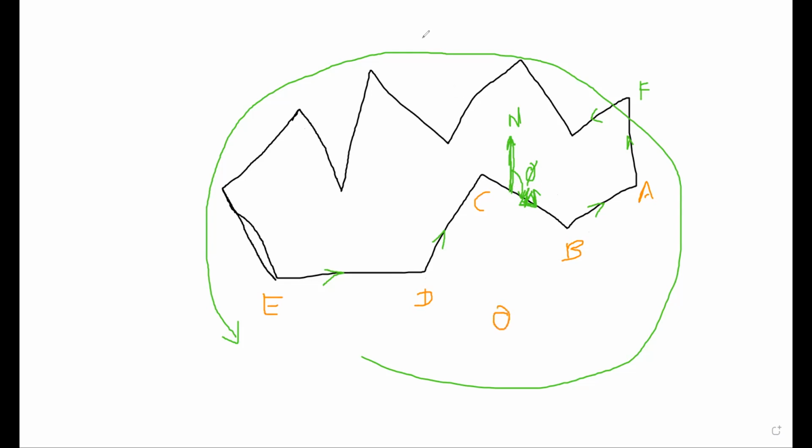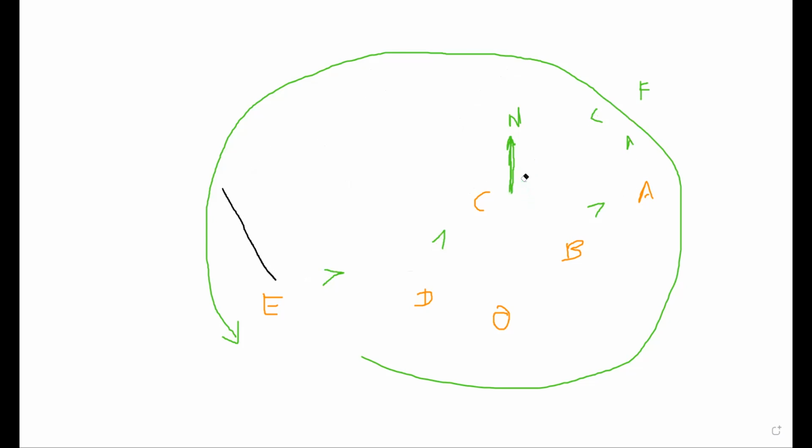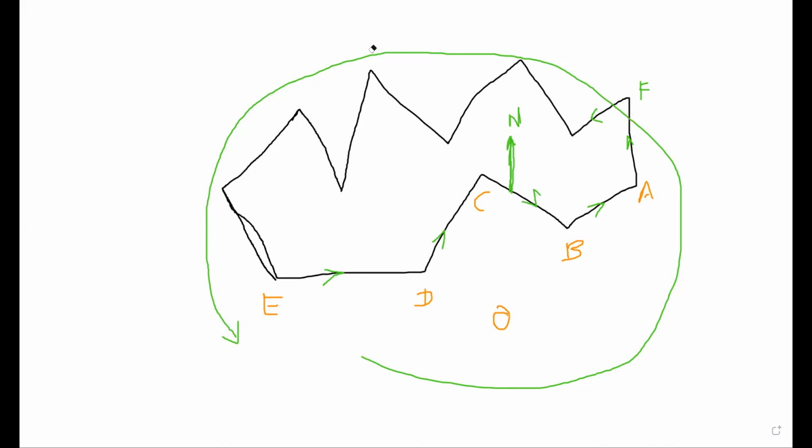If you have measured the other bearing, let's say, not by mistake, if you have measured this bearing, BC, you need CB in order to fill this traverse sheet, because CB is our movement direction.